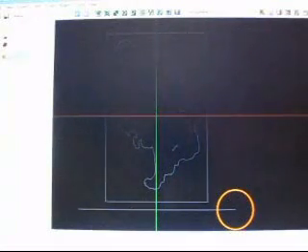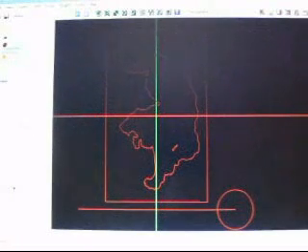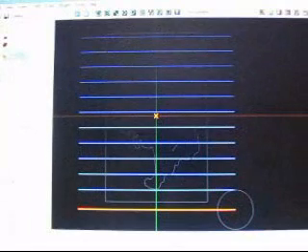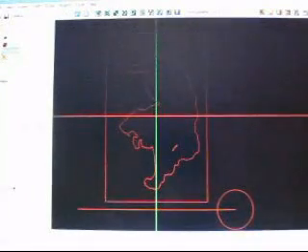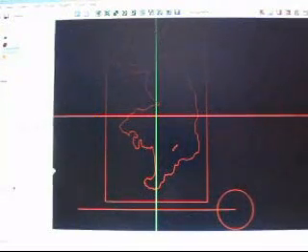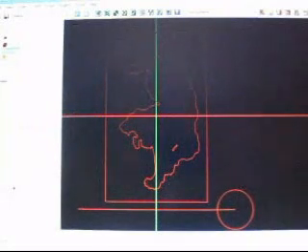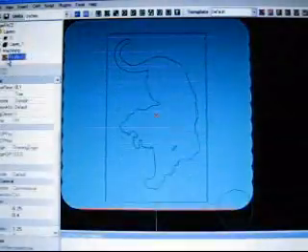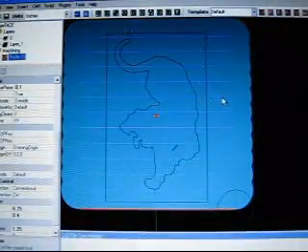Now, one quick little thing in the software that I want to show you. If you select up here, you can select your profile cut, your machining operations, or this whole entire machining thing. If I change this over here where it shows cut width, let me bring this out just a little bit, if I double click on that to make it go from false to true, now when I hit this, you'll see the cut width.